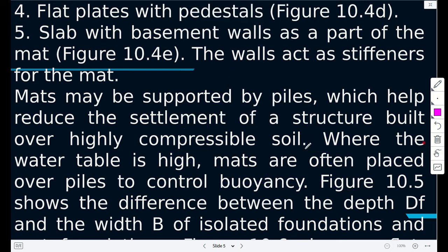This is the same idea as when you're doing a hard pan. Very common when you're dealing with soft soil, you first put rocks. That's the idea also, because the rocks will make something that looks like a hard pan.